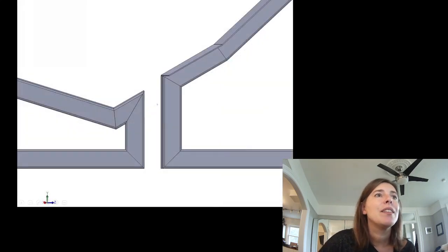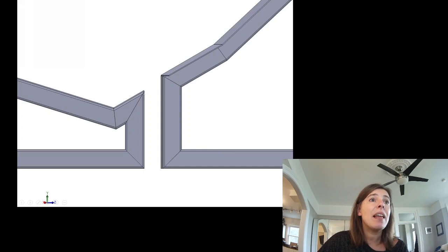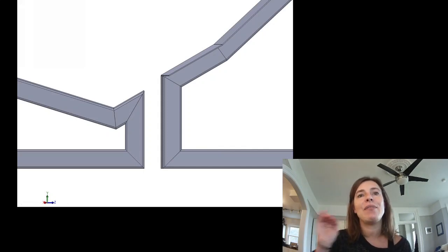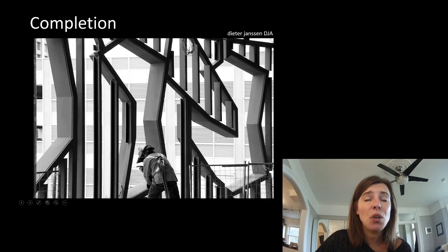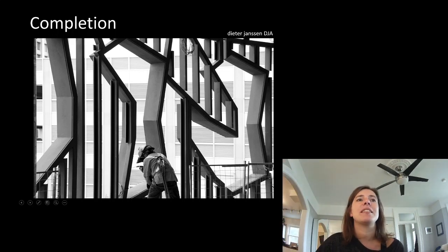This one's a really good one. You can see it right here. That you would look at this on site and be like, oh my God, we have a problem. But this line here and this line here needed to be perfectly aligned to each other. So if you put a string and glued it here and a string and glued it here, it should be perfectly flat against the face of those two panels. So we took a ruler, not even a measuring tape, but an actual ruler, and held it up. Again, we reached through and held it up flat against that surface, and everybody's anxiety went way down.